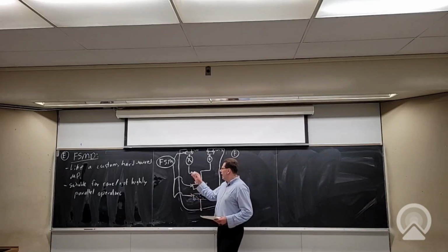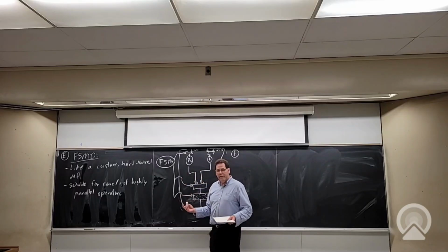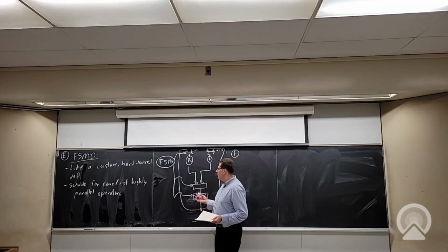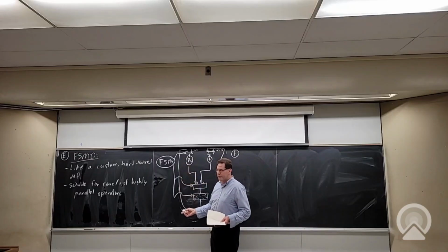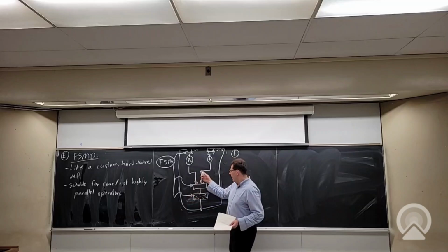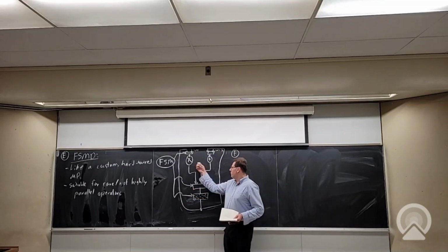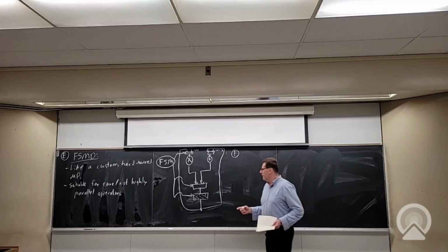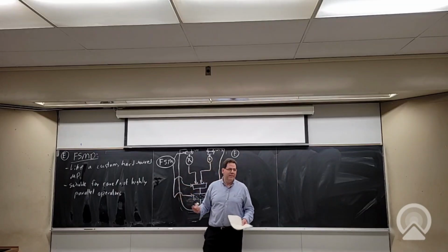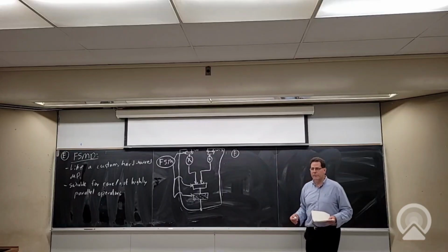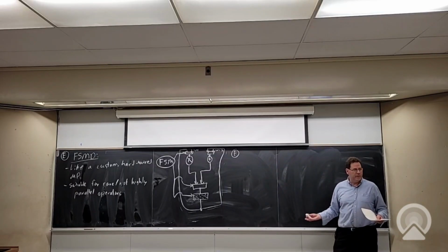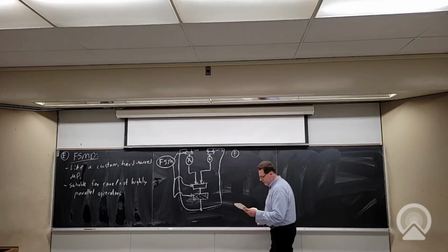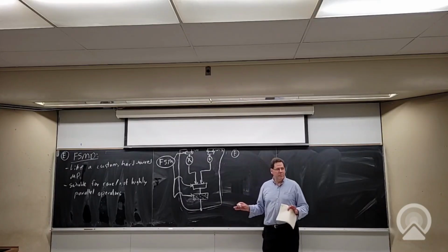And in assignment 1, you're going to build a shared operator version of the Taylor series computation you have to do, which is basically a shared operator version is another way of saying finite state machine with a data path, right? So you're going to build the minimum number of operators you can, and you're going to gradually build up the computation by having a state machine control it and add everything together. And then you're going to check how efficient this is versus the more streaming style calculations that you did in the earlier part of the assignment. So you'll get experience in writing this. Is that clear to everybody?